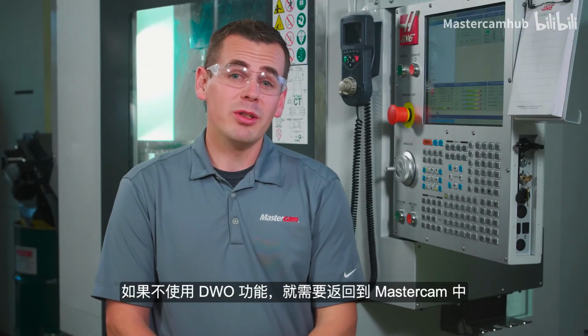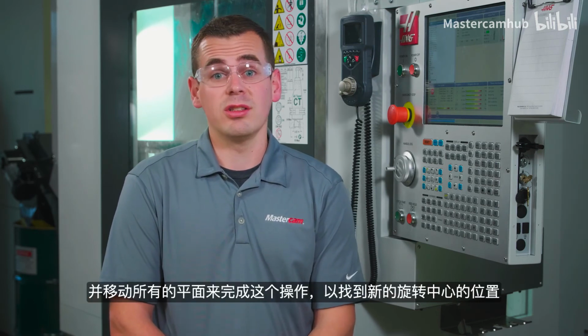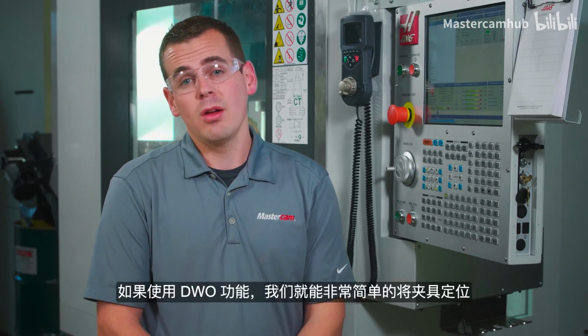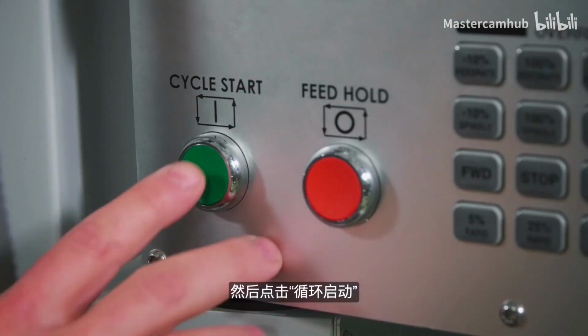Without DWO, you would have to go back into Mastercam and shift all the planes for this operation to reflect the new location relative to the center of rotation. With DWO, you simply pick up the new fixture location and hit cycle start.